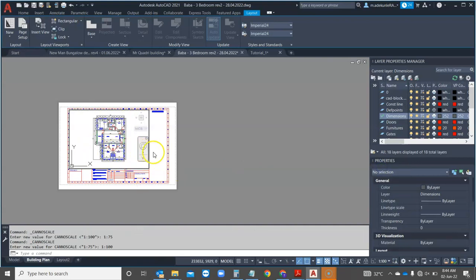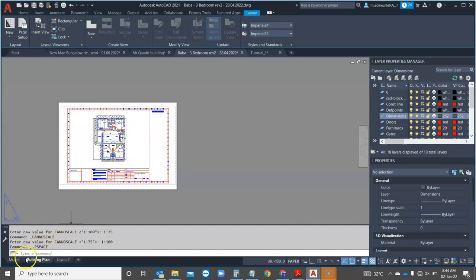So once done, you can lock it, because it's very important. Maybe when you go back, you don't want to mistakenly alter the position of this drawing. So I'll lock it. Then we must not forget I had something highlighted here that I wanted to show. So I'll go back to model space.